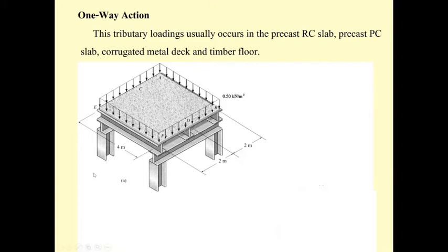And then from this picture, you will build the column. When you finish building the 4 columns, you build the big beam here and here. And then you may build the small beam crossing between the big beams, this one and this one.